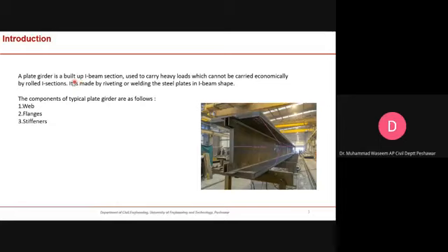Okay, it is a built up and mostly it is an I section. I section means like this one. Okay, so this is a built up section, it is not a hot roll section first of all. Okay, so if I grab my pen, that plate girders and what is the difference between a wide flange and plate girder. So you should know that plate girder is not a hot roll section.